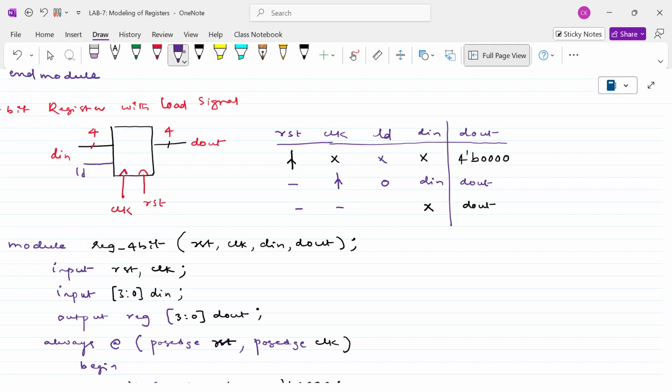That's called synchronization with the clock signal. That's what we have seen for the reset signal also. RST, if the clock edge is there and the reset signal is there, then it is called synchronous reset. If the reset has the highest priority and does not follow the clock, even if the clock is available or not, doesn't matter. Whenever the RST is there, then the output is defined, then it is called asynchronous, right? So that's what we can write.